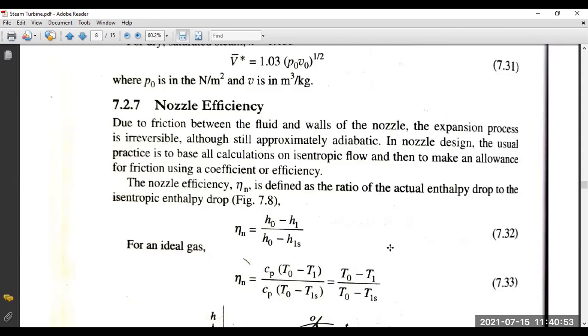And then what will happen if it starts flowing again from the remainder part of the flow itself? The flow is convergent up to a certain point, and after that it is again divergent. That point where the cross-section is minimum is known as the throat of the nozzle itself, and we assume that the fluid at this nozzle is at stagnation phase. When it is here, it is brought to rest because the area is dropped considerably from the inlet to the outlet itself.